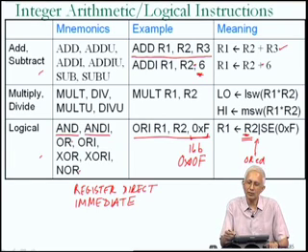So, the question is, how do you generate a 32-bit value to do the OR out of the 16-bit immediate which has been specified in the instruction? And the answer is that it is done using sign extension. Once the sign extension is done by the hardware, it then does the OR using a simple OR circuit. I am using the same operator for OR that you are used to seeing from C. The C OR operator is that pipe, which is what is used in this example.